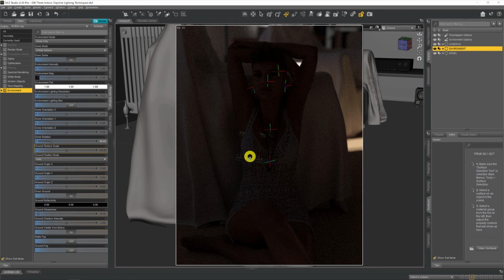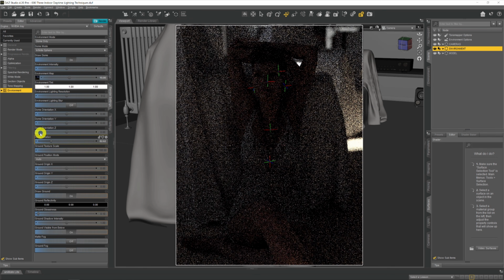We've got this natural light coming into the room. And what we want to do, it's a bit dark, it's a bit dim, we want to brighten things up. Now, there's a number of ways that we can do this, okay? We can come across to the environment map or the environment intensity over here, and we can change it. We can increase the map and we can increase the intensity. Let's say it's currently on 2. Let's say we move it up to 10.